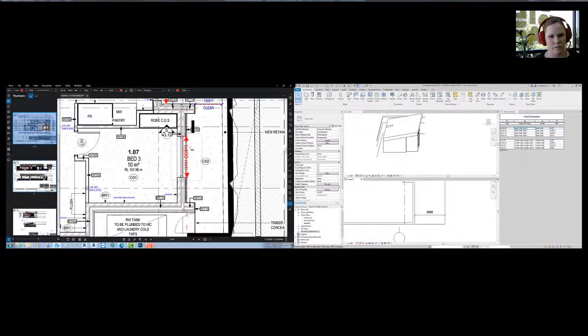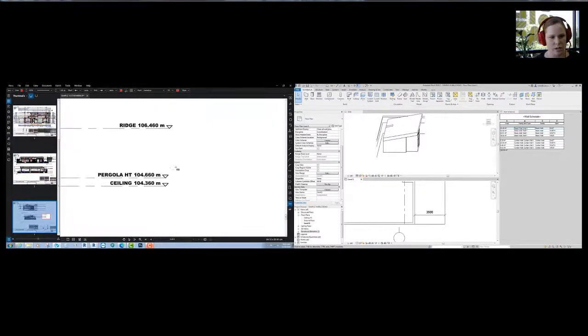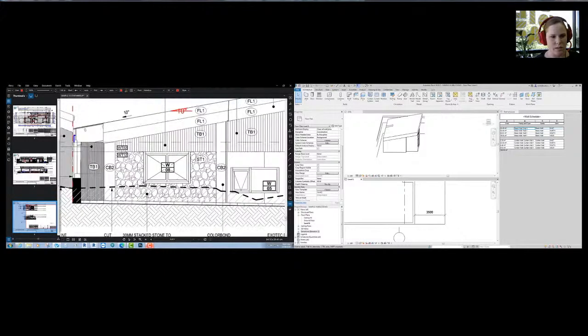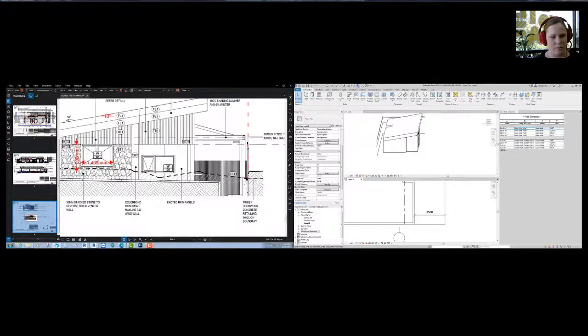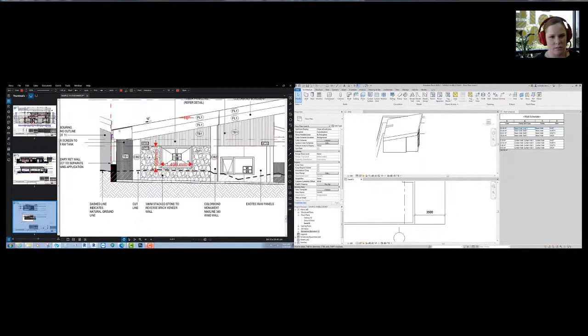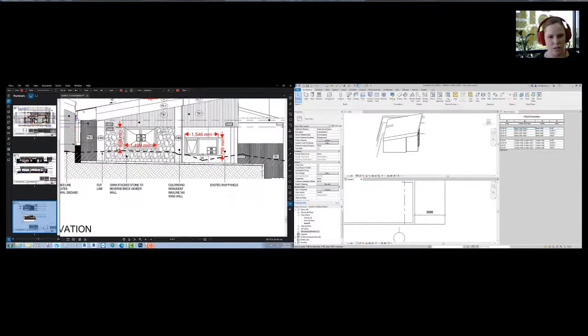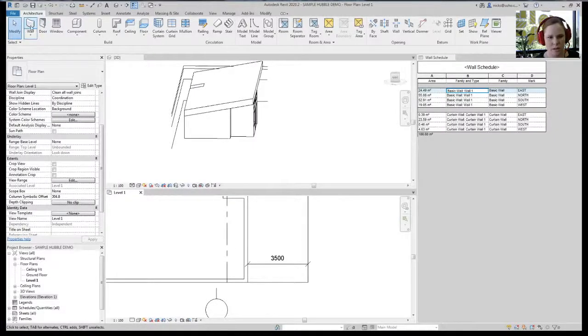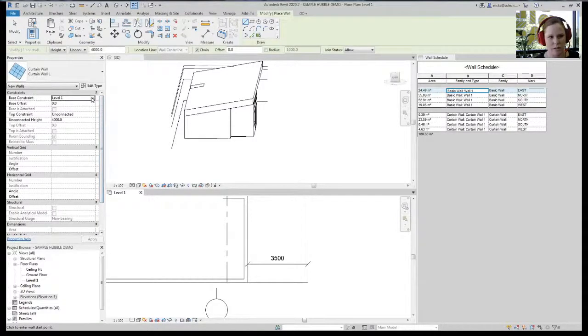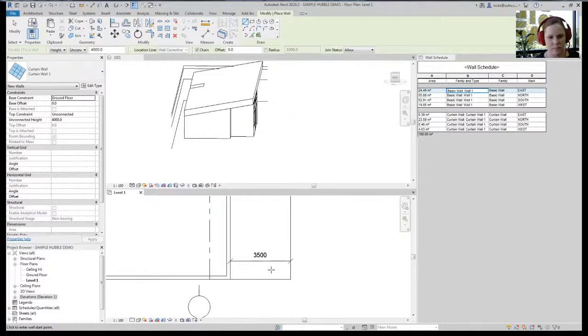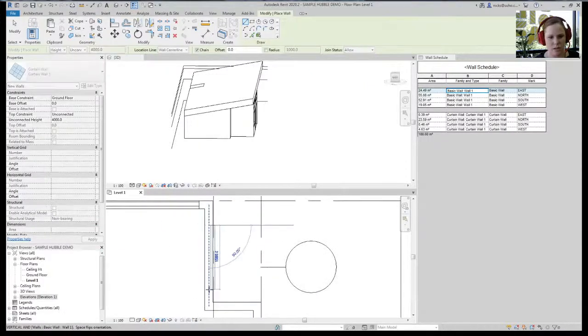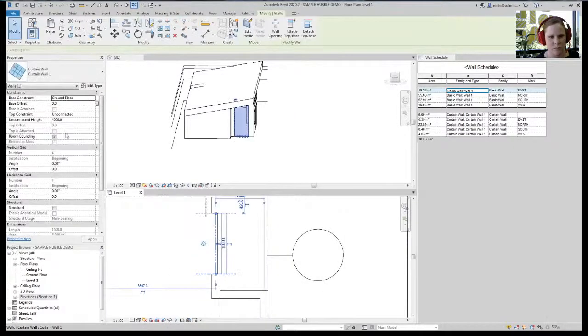A window. I'm not going to do the inset for the rainwater tank in the plan. We'll leave that off in this instance. Let's focus on the other parts of the building. Okay, and what's the head height? Good. There we are. More height and width. Okay, now we're going to embed those eastern windows. I'll put them in the wall. So this one's in the kitchen. And then we're going to allocate its height and base offset.